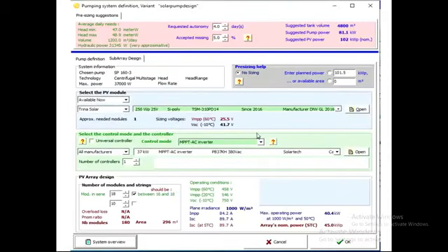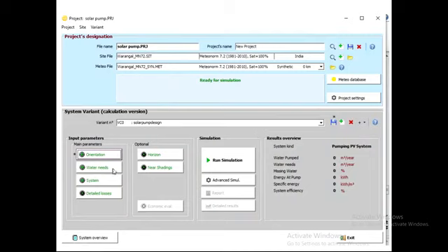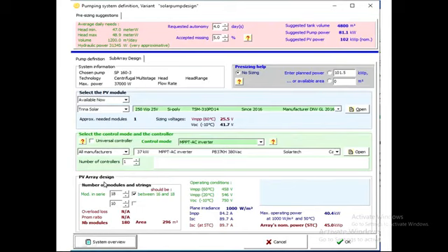Then here you have to define the system. So right after completing the water needs, click on the system. Click on the system, then you will get this window. When you open this window, based on your water needs, it will suggest hydraulic power. By default you will get hydraulic power 31.3 kilowatt, and suggested power is 1 or 2 kilowatt. It is near to our values.